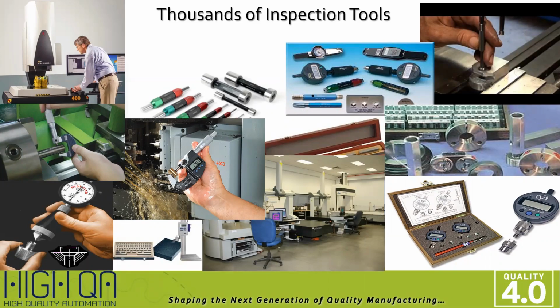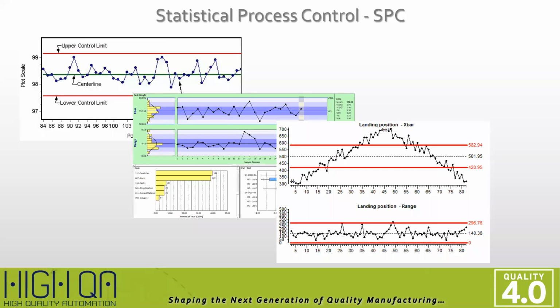If we look to another source of data, SPC, for instance, this is also a very good tool to try to anticipate what's going to happen: the trends of a part, consistency, stability. But actually, what happens is we upload data after we inspect the part, and then there is a great chart, X bars and histograms. But can we get it in real time? Can we get something now so that we can fix the process? So again, data is great, but if it's not information, then it's a challenge.